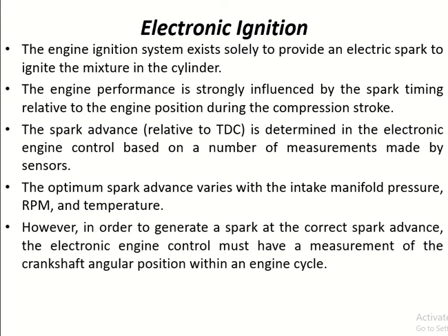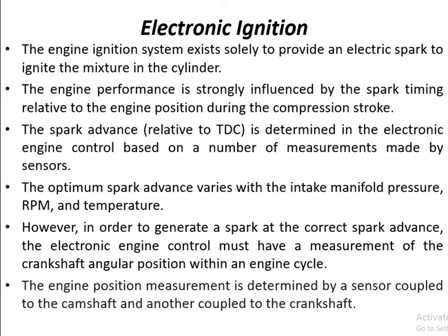However, in order to generate a spark at the correct spark advance, the electronic engine control must have a measurement of the crankshaft angular position within an engine cycle. The engine position measurement is determined by a sensor coupled to the camshaft and another coupled to the crankshaft.